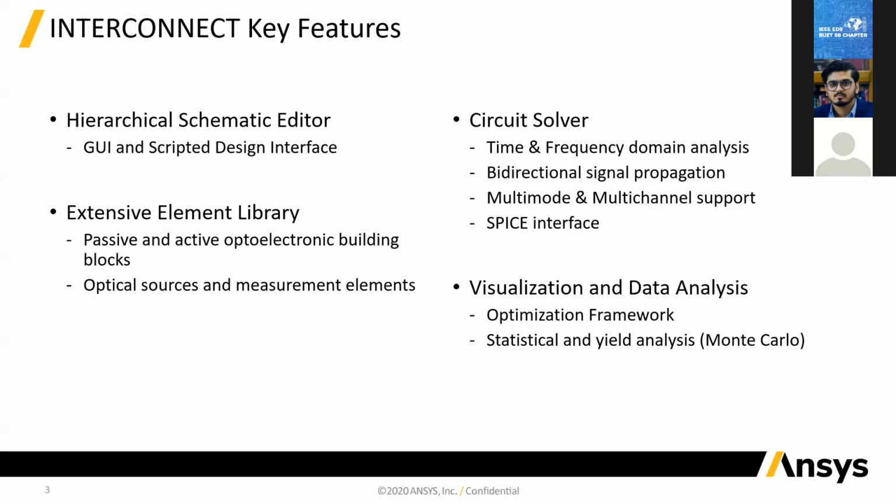In terms of circuit solver, as I mentioned, it comes with time and frequency domain analysis. The optical signal propagation in interconnect is fully bidirectional, and it also supports multi-mode and multi-channel support. So if your device supports both TE and TM modes, you can just run a single simulation to see how they propagate through your system, as well as multi-channel simulation is done in a single run. And then it also has a SPICE interface, so you can hook it up with external electrical solvers like Spectre, and then run electro-optical co-simulation.